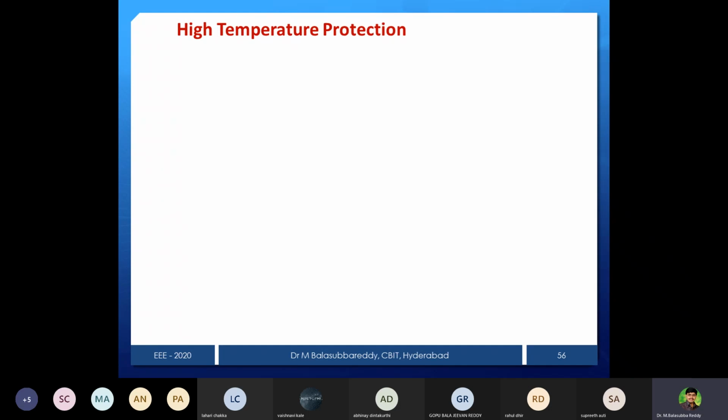The resistance of that junction will drop, allowing more current, and in this cumulative process the temperature across that junction increases beyond the specified limit. Then junction J2 breaks down.